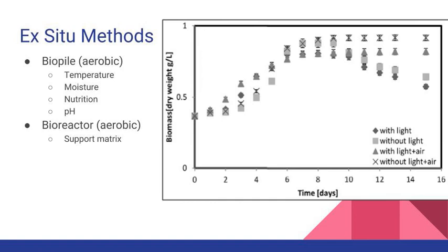Moisture from the leachate collection system may be treated and then recycled back to the contaminated soils. Nutrients such as nitrogen and phosphorus are often added to the recycled water. Alkaline or acidic substances may also be added to the recycled water to stabilize pH.